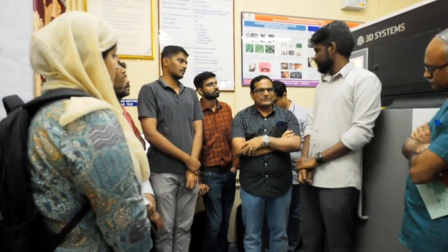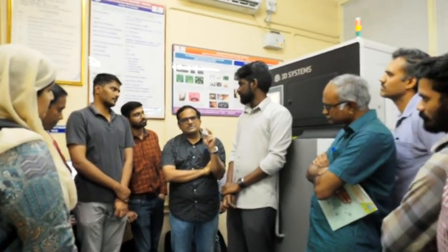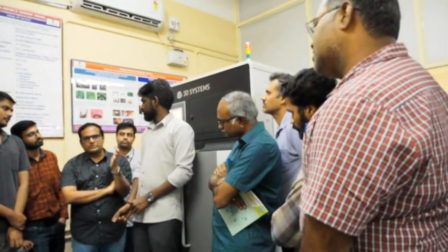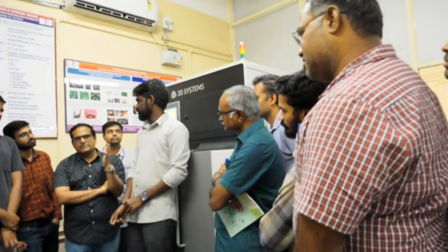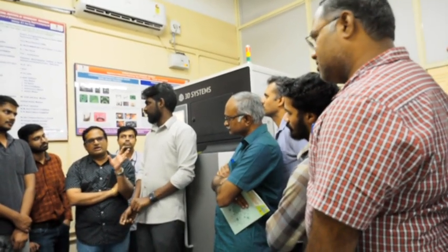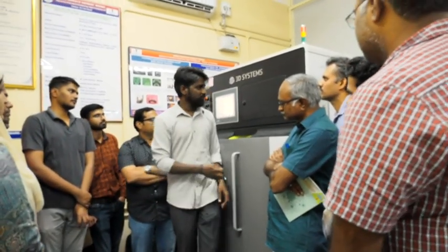So right now we have that sieve. Always we are using metals, so oxidation is a major concern. Not only that, we need to pump the inert gas also. So we have two options. One is nitrogen. Nitrogen goes with all non-reactive materials like steel, other than aluminum and titanium. For titanium and aluminum, we need to use argon. So we have two: nitrogen and argon atmosphere, right?